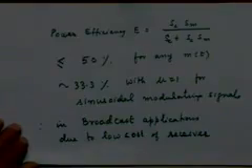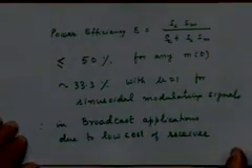Okay. So what is the alternative? There is no alternative. Alternative is to go for DSBSC. But how would you make the carrier? Can be done. It's not undoable. All that I said is it's more complex. So if you agree to pay the cost for that complexity of the receiver, you can do it. It's perfectly doable. You can have a synchronous receiver, right? The fact that I am doing this doesn't mean that we can't have a synchronous receiver, if you are ready to pay the cost for it.